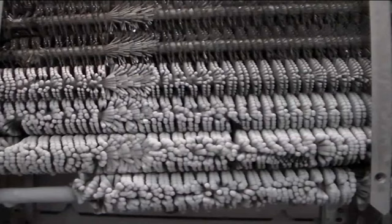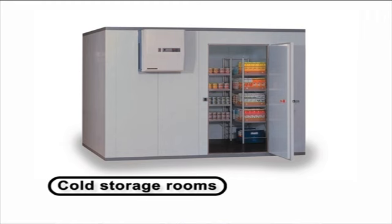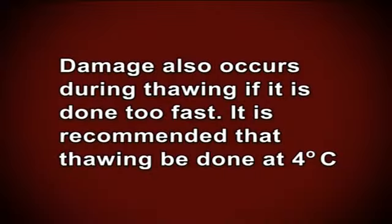Products near the refrigerator coils or at the bottom layers of refrigerator cars and trucks are most susceptible to freezing injury. To avoid freezing injury, the rail cars or trucks should be heated during transportation in sub-freezing weather, and adequate air circulation must be provided in cold storage rooms. Damage also occurs during thawing if it is done too fast. It is recommended that thawing be done at 4 degrees centigrade.